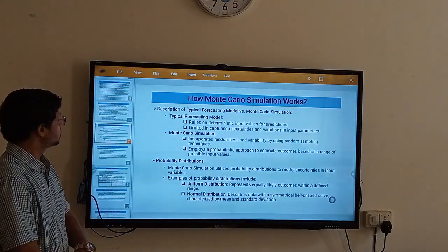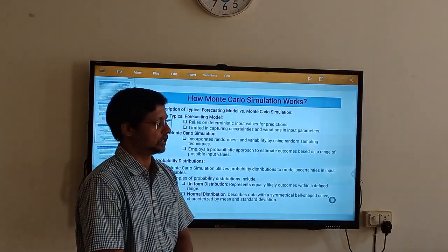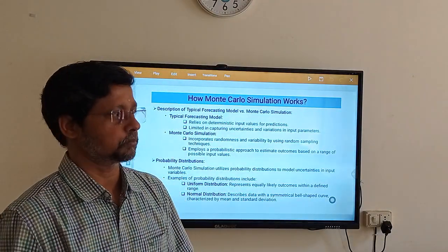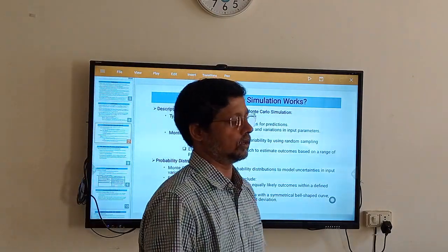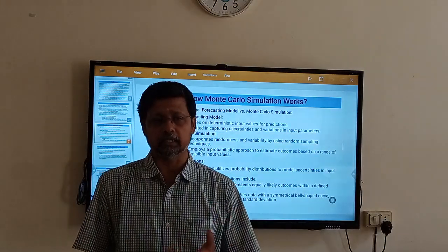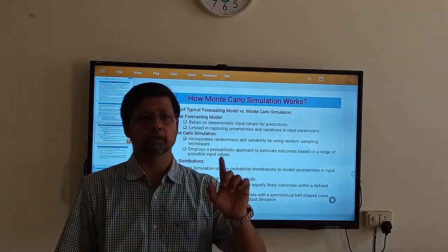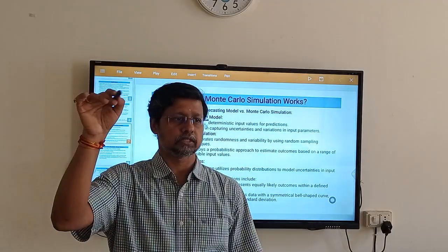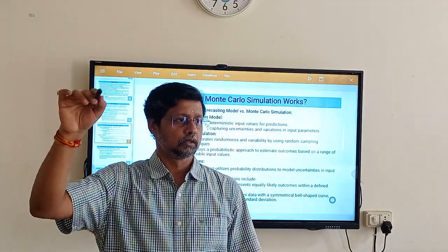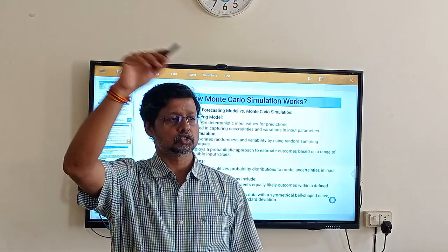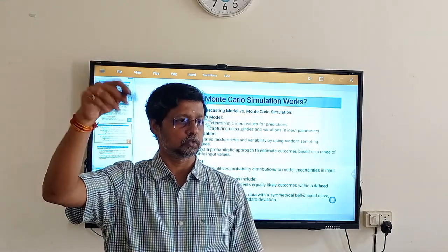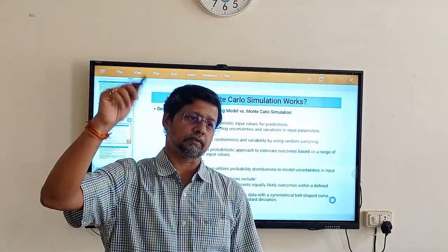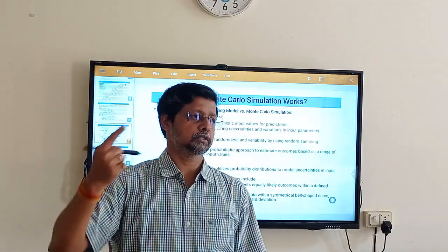How are we able to do it? Because it generates random samples. That means, for example, is the number of samples infinite? The answer is no. Remember that the number of samples you are taking, n, is always finite, isn't it? You write fs is equal to 2 times fm, so that 2 is n. In instrumentation we have already discussed that this 2 will not be enough. There will be a variable value, 1 to 5, 5 to 10. But in any case, 5 to 10 is also a numeric value, and 1 to 5 is also a numeric value.